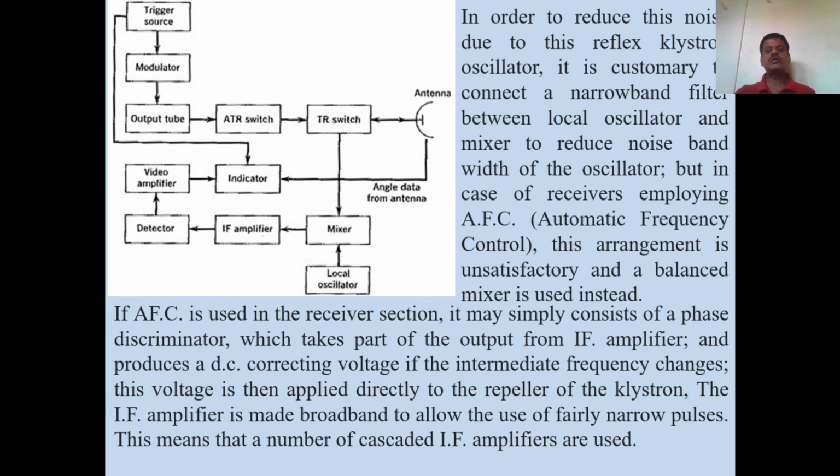In order to reduce the noise due to the reflex klystron oscillator, it is necessary to connect a narrow band filter between the local oscillator and the mixer to reduce the noise bandwidth of the oscillator.